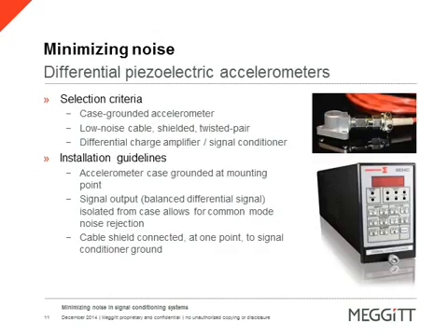Another form is differential piezoelectric accelerometers. All of our differential piezoelectric accelerometers are case-grounded. This is the most common type. They must be used with low noise, shielded, twisted pair cable, and must also be used with a differential charge amplifier or signal conditioner to provide the technique of common mode rejection. Sensors of this type are primarily used with noisy jet engines and test cells. Common mode noise rejection is very key to help eliminate amplification of unwanted noise.